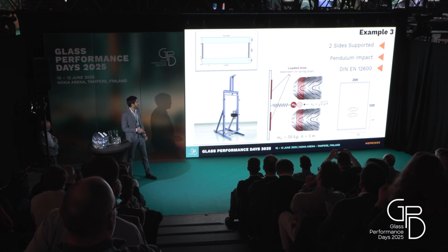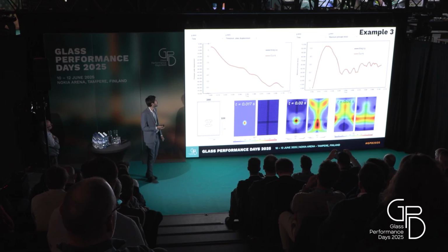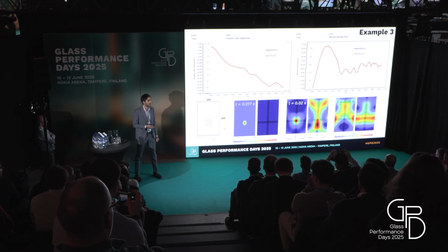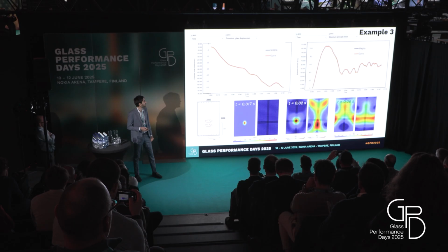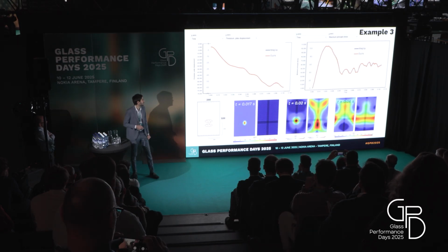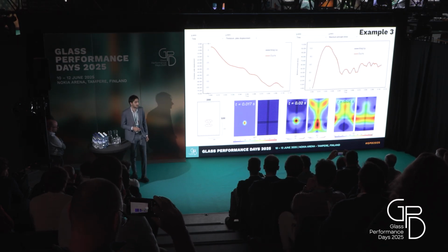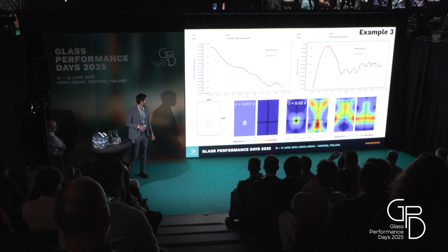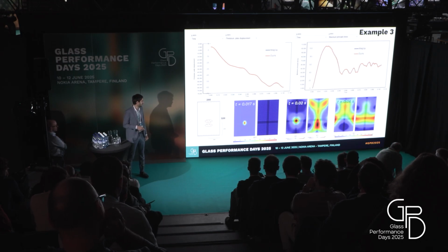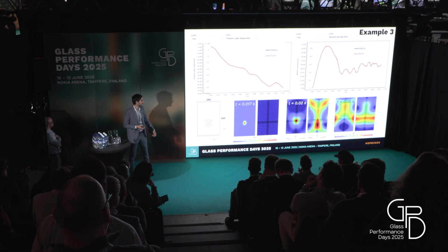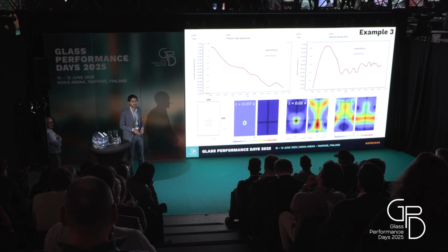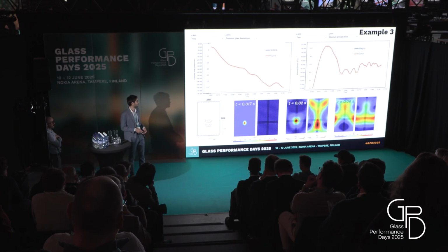So we see the comparison, MEPLA versus ours, for the maximum plate displacement and maximum principal stress. You see they are very similar. On the bottom are the maximal principal stress diagrams for 3 typical times. The first one is when the pendulum is approaching the upper plate, and you see the 2 ellipses for the load on this surface.